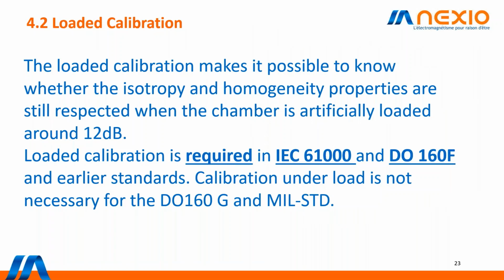So now the loaded calibration. The loaded calibration makes it possible to know whether the isotropic or homogeneity properties are still respected when the chamber is artificially loaded around 12 dB.